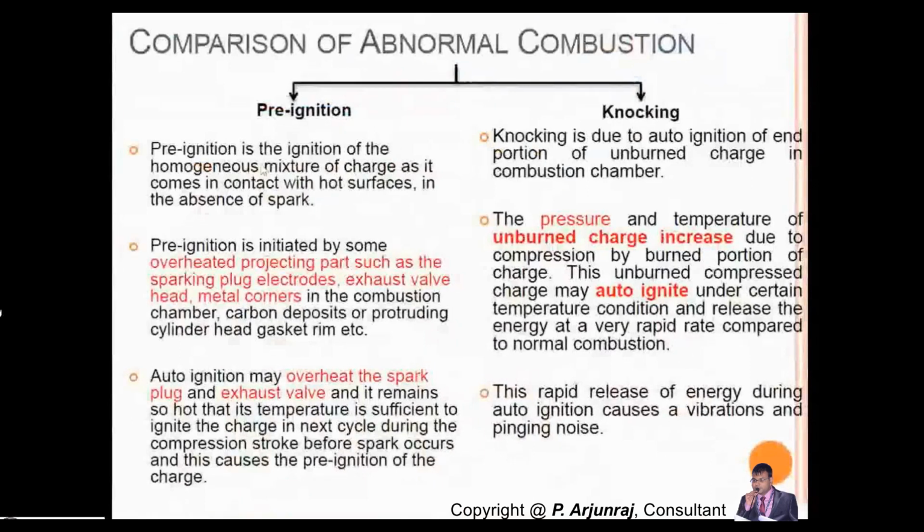So there is one more term called pre-ignition. It means the ignition will happen well in advance. This ignition will happen when the charge comes in contact with a hard surface in the absence of spark. So this phenomenon is called pre-ignition. And again, this pre-ignition is initiated by overheating of a projecting part. It can be the spark plug electrodes. When it gets heated up, you get a pre-ignition.